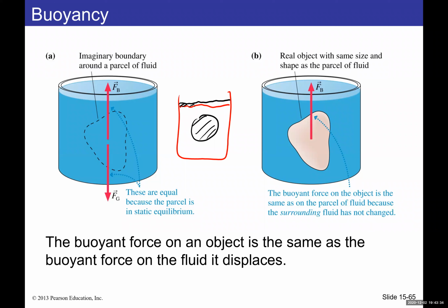What we can say is that when you submerge something into the water, it displaces a certain amount of water. If I take only the amount of water that has been displaced and find its weight, the weight of the displaced water, this is what the buoyant force is equal to. So the buoyant force is basically equal to the weight of the displaced water.